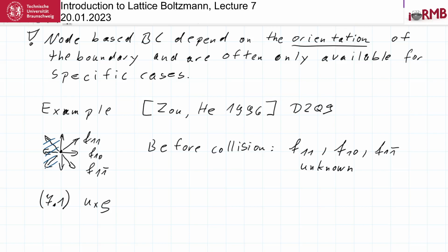And actually it's not even a velocity boundary, but a momentum boundary because it is ux times rho that we specify. And this is specified by computing the moment, and so this is, yeah, I omit the lattice units here, because we usually do this.